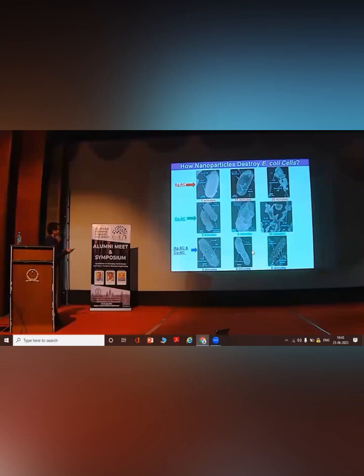Because as you can see from the time scales here, silver takes 25 minutes to completely destroy, copper takes 10 minutes, but there is some synergy when you give silver and copper: 8 minutes. So going from 25 to 8 minutes, there is a factor of 3.5, which enhances the kill rate, and that translates directly to 3.5 times larger throughput of treatment of water in a filter in a domestic batch quality.